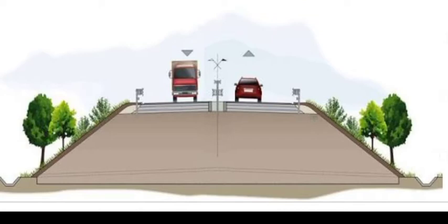The essential requirement of soil properties considered suitable for highway embankment as per IRC is: liquid limit should be less than 70%, plasticity index should be less than 45, and free swell index should be less than 50%, and maximum laboratory dry density on compaction, especially heavy compaction or modified Proctor test, should not be less than 1.52 g/cc, that is 1520 kg per meter cube, for an embankment height up to 3 meters, and 1600 kg per meter cube for embankment height more than 3 meters.